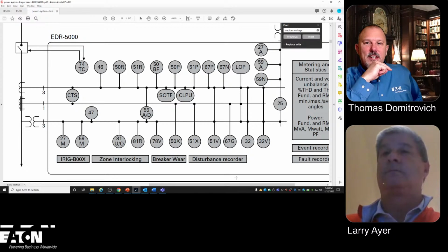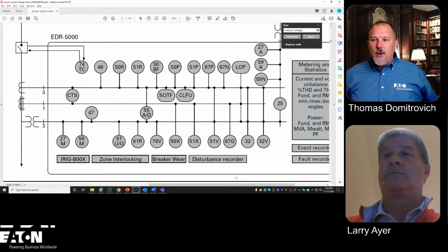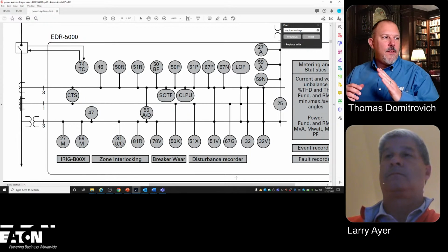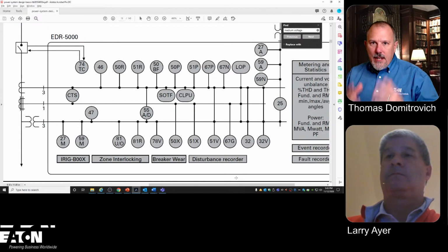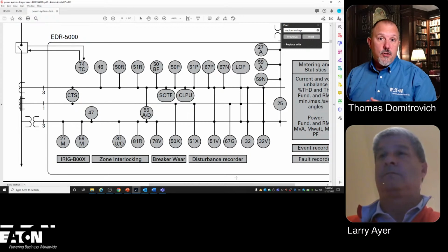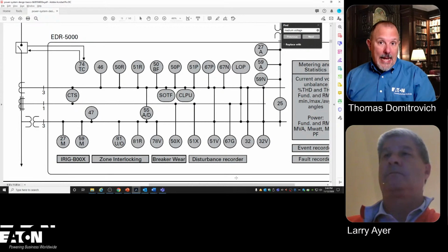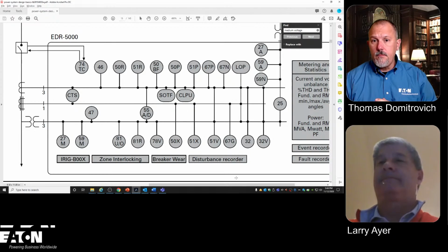Al said it right. Al says you're getting into the IEEE world, and Larry, that is part of what this task group is trying to address. When you get into the medium voltage world, everybody thinks that's the IEEE world. That's not the National Electrical Code. The IEEE is the group that governs or manages the NESC for utilities. Sure, it gets pretty technical once you start getting into all of the different types of protective relays that you would have to employ, or may have to employ.